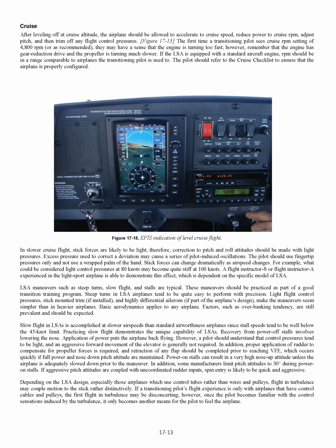Depending on the LSA design, especially those airplanes which use control tubes rather than wires and pulleys, flight in turbulence may couple motion to the stick rather distinctively. If a transitioning pilot's flight experience is only with airplanes that have control cables and pulleys, the first flight in turbulence may be disconcerting. However, once the pilot becomes familiar with the control sensations induced by the turbulence, it only becomes another means for the pilot to feel the airplane.